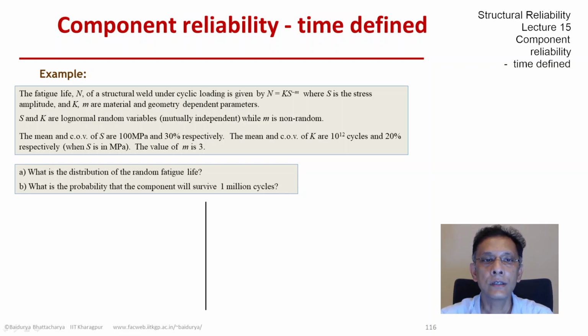So this kind of gives an idea about what might be done in an accelerated test. This formulation really does not make it more physics-based. We are still treating the fatigue cycling and fatigue failure as a black box. We just have parameterized the problem with the random stress amplitude.